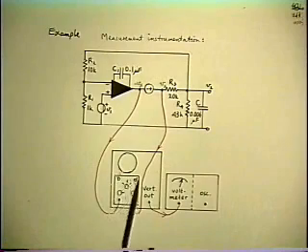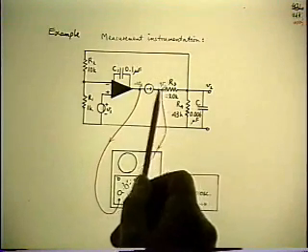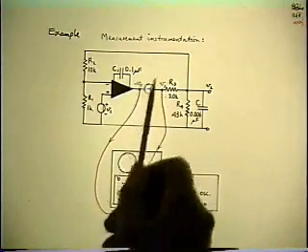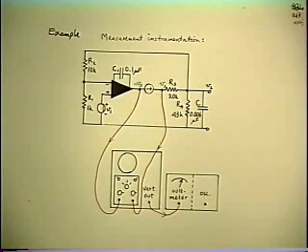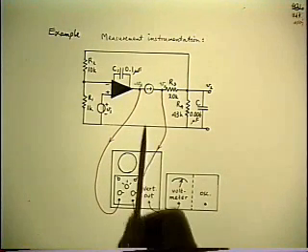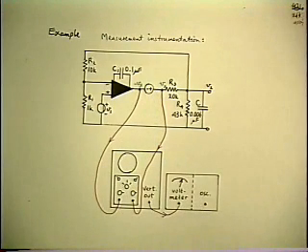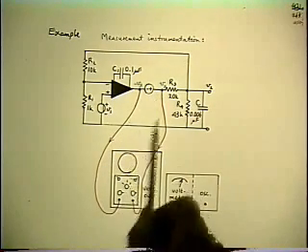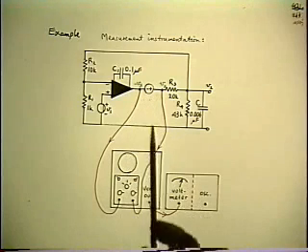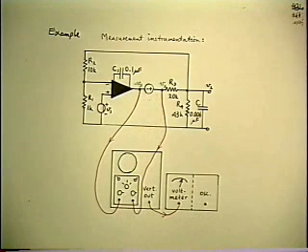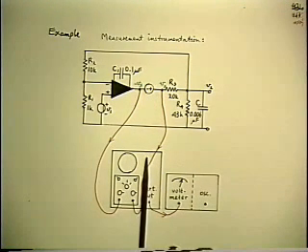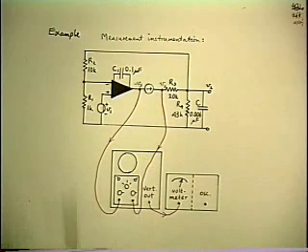So for each frequency, you measure the magnitude of Vx and the magnitude of Vy and the magnitude of Vz. And you plug into that formula and you find the corresponding phase angle of the loop gain at that frequency. Now, you can actually modify that by iterating the design technique, and you can refine it in order to overcome some difficulties to do with accuracy at certain conditions, but I won't stop to go into that.